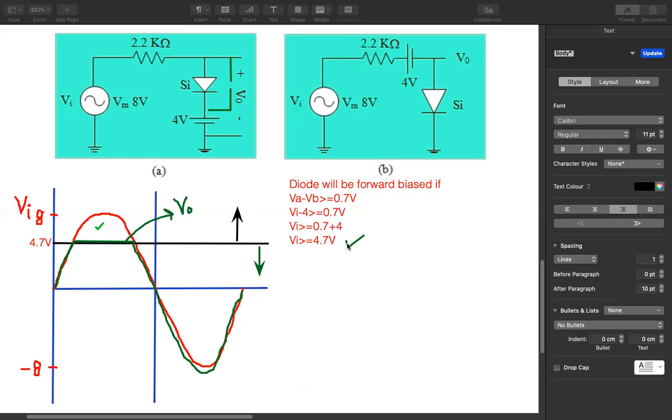The very first thing is to derive this transition equation, the transition conditions. Draw a line equivalent to this. Make marks that this is for forward bias, this is for reverse bias. Once you have done this, now forget about any external DC power supply, whatever input voltage, forget about that. Now simply draw the equivalent circuit for forward bias, and now see what you are getting. Then draw the equivalent circuit for reverse bias. Now see what you are getting. Okay, so for forward bias simply draw this line, whatever output conditions arise in this region, you draw them.